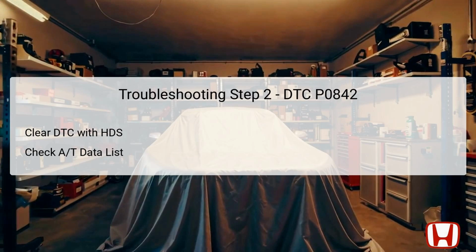Next, clear the DTC using the HDS. Clearing the code will allow you to see if the issue persists after being reset or if it was an intermittent error. After clearing, check the second pressure switch in the automatic transmission AT data list while ensuring that the vehicle is not in second gear.